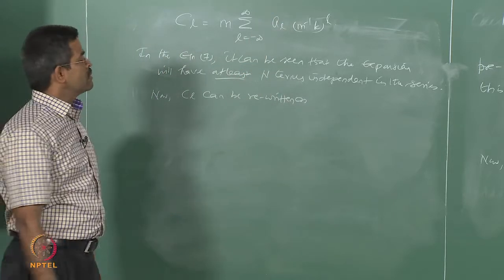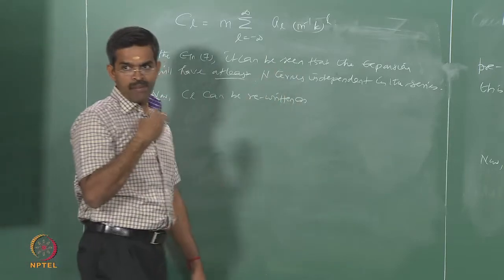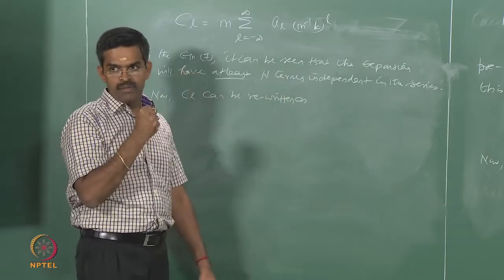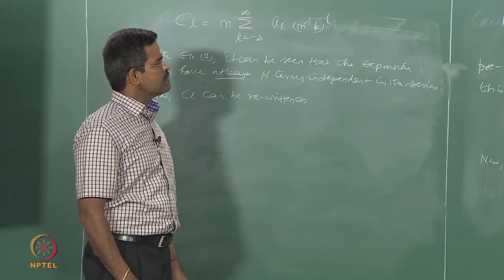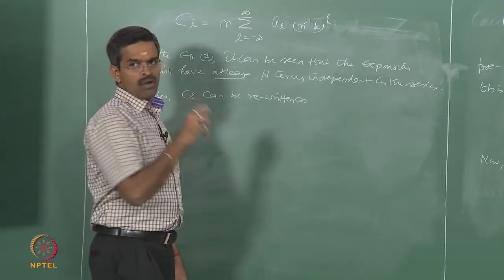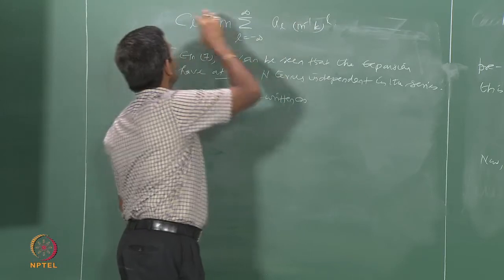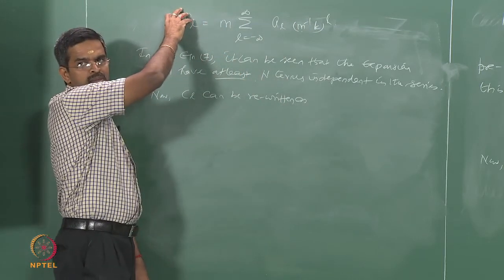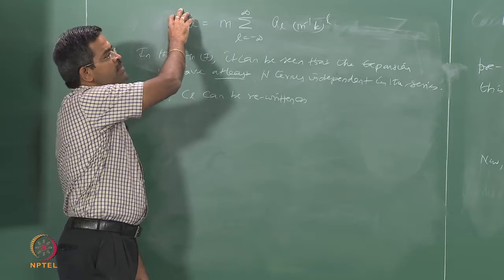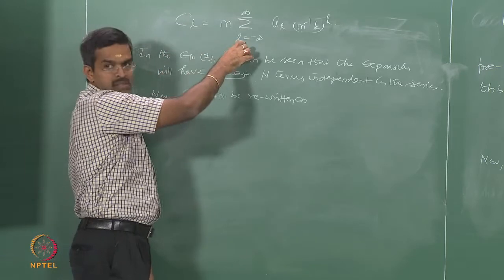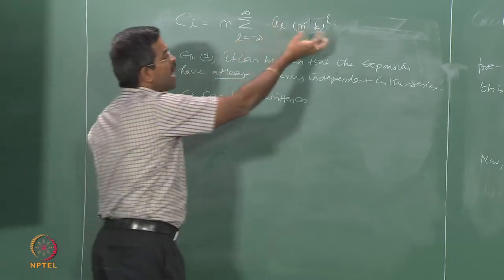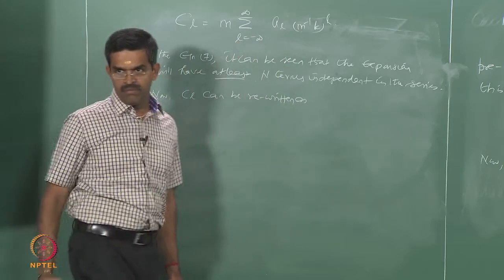So, at least there will be n independent terms, but I am interested only in catching the independent terms. What it means is, if you are looking for a contribution of k and m as a damping matrix in your Caughey damping coefficient, after a specific eigen number, the contribution of k and m will get repeated.